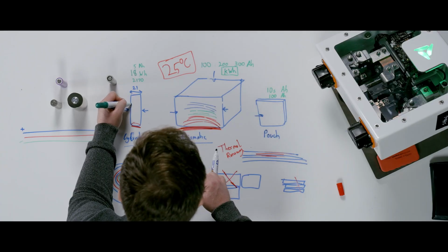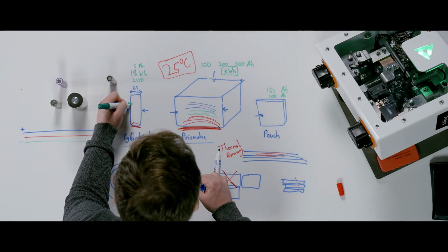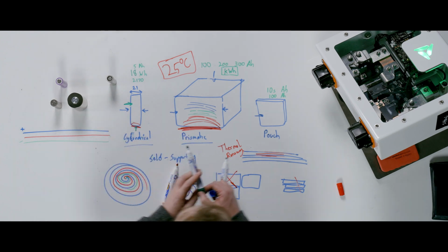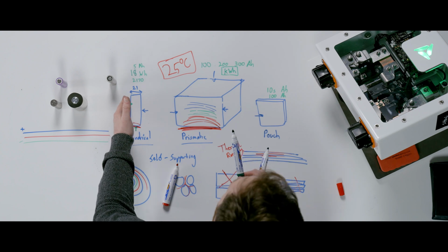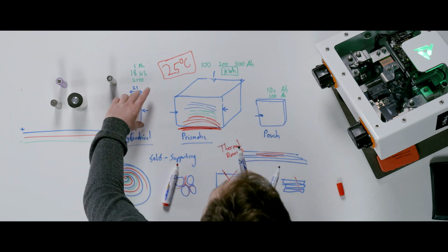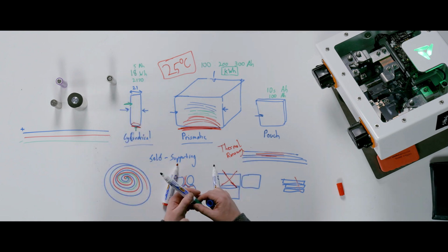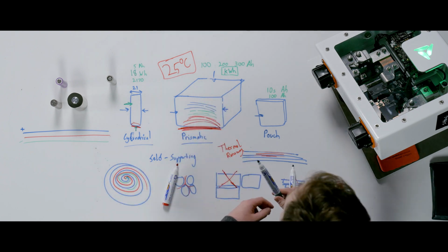So actually, to cool the side of the cells here might not be the best, because you've got a very high thermal resistance going this way versus going this way. But in all real practical packs, getting the most contact area on the battery cell, and for other pack designs, it is actually in practice better to cool from the side of a cylindrical cell in all real-world applications and real-world examples. With large prismatics, the same applies.